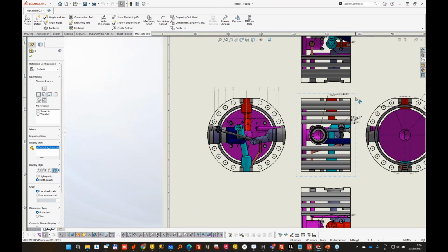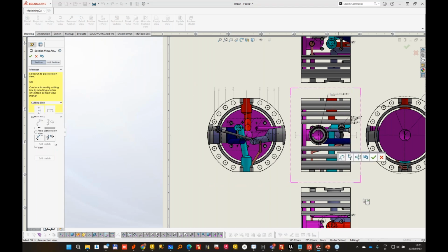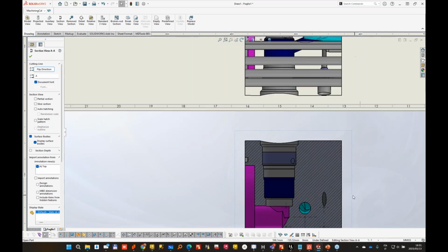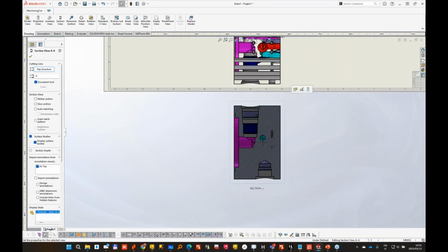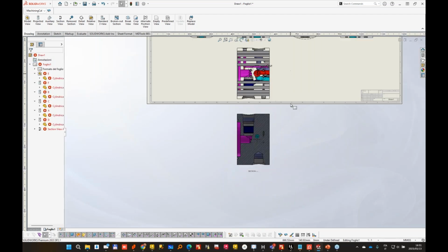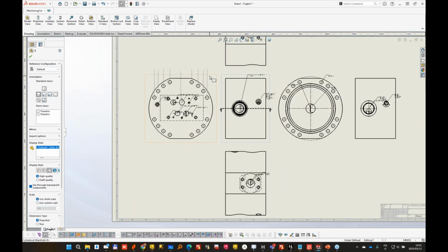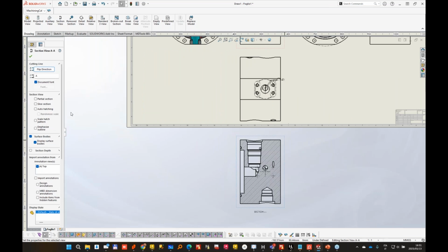Whenever you need, you can make a cross section. This is done not with MDTools command, but with standard SolidWorks commands. So as an example, we could make a cross section just to show the intersection here. And the aspect is controlled really by SolidWorks. Either you want to display according to the view, or you can do all black and white, or show the internal colors in either cross section or wherever you need.